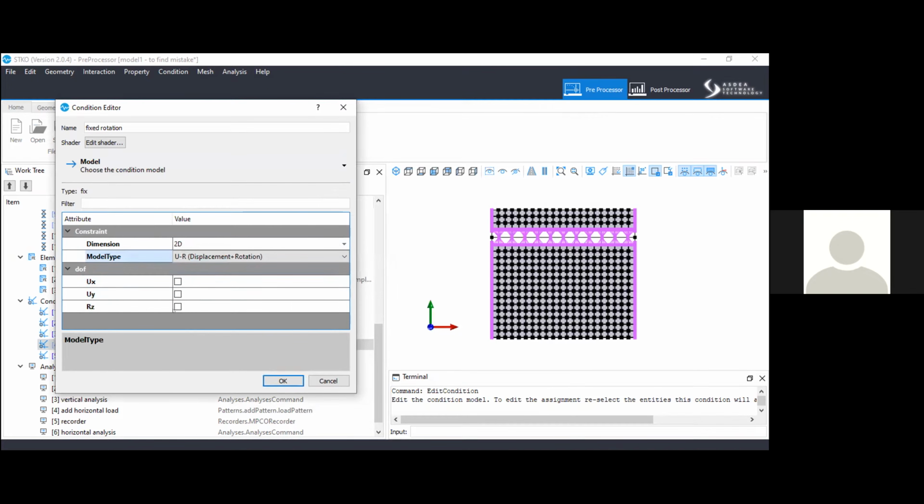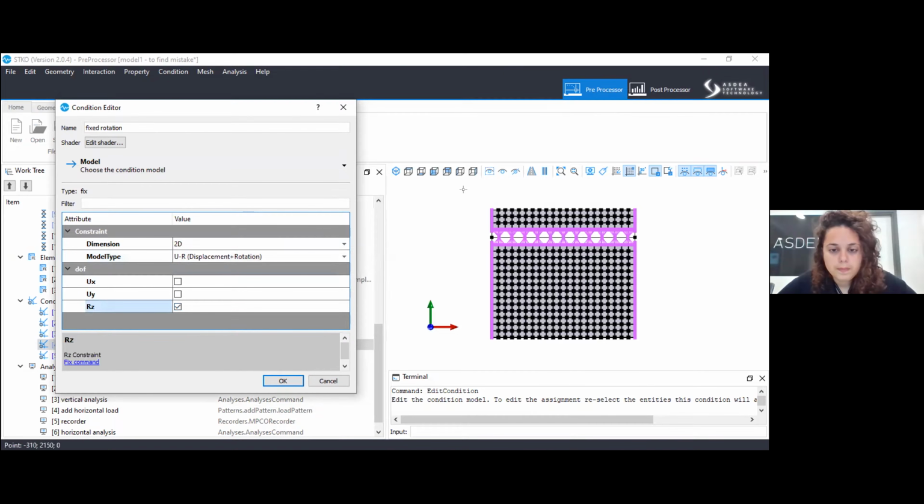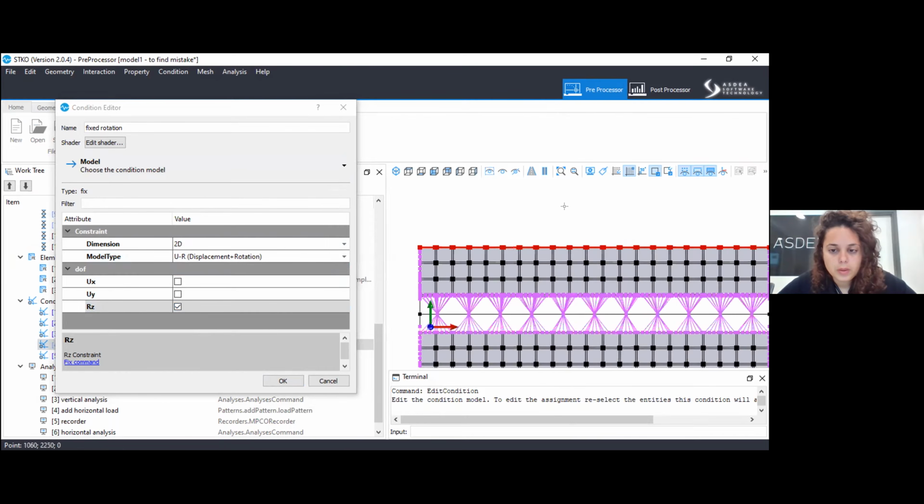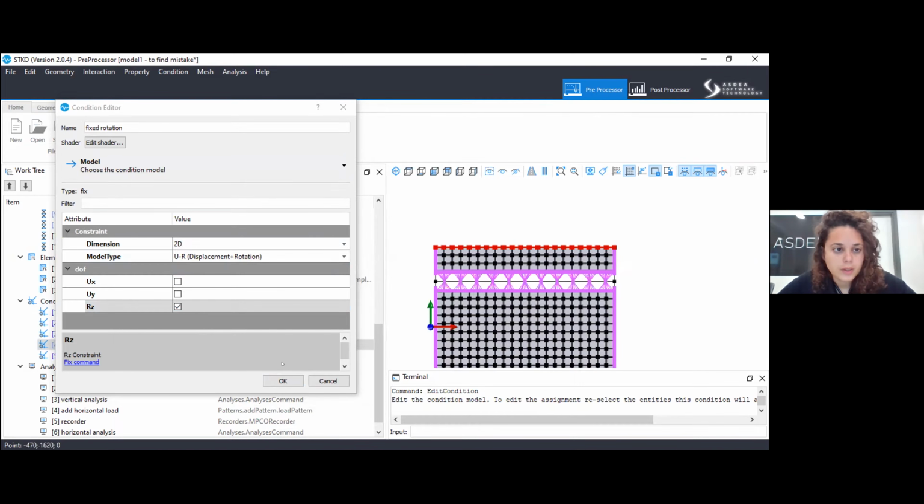Do I need to fix it? You can use a fixed rotation like this if you want. You don't need the equal DOF. I think in the model of Massimo, he had two geometries, and on the top he had an interaction, and then he applied the equal DOF to the interaction, but the interaction was needed because the two geometries needed to be connected.